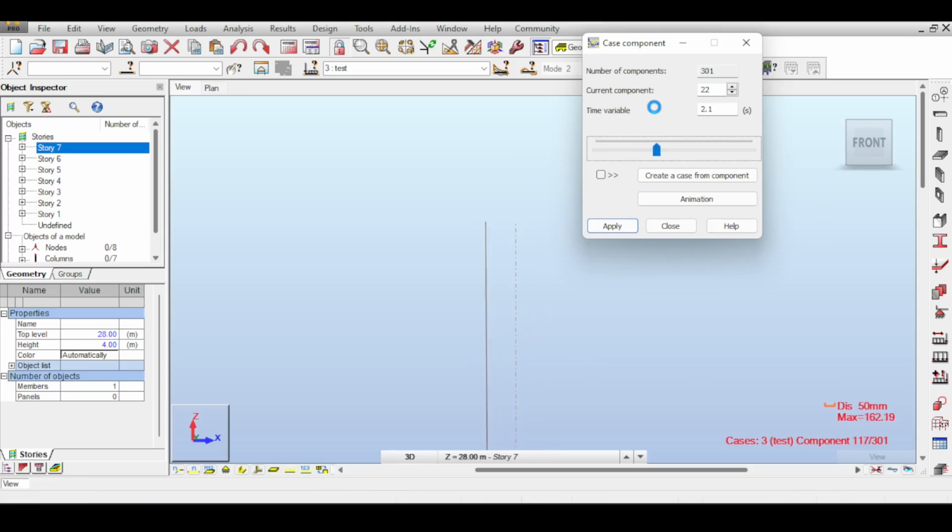Oh, and just to make sure that you understand this, the force will not keep repeating. Your analysis is 30 seconds, but the force was only applied for 10 seconds, and this means that the structure will keep vibrating. Now, I think there is no damping based on my little expert eye. I think damping is not included.